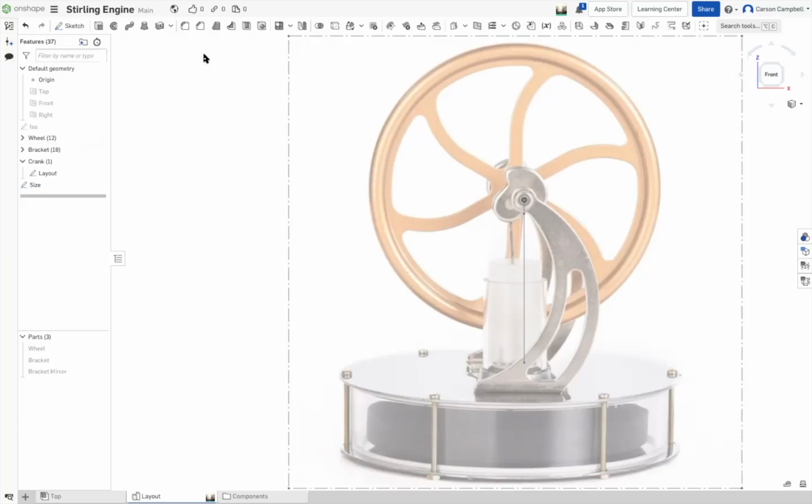It's also one of the reasons why I don't like dealing with US dimensions, because their nominal is in the middle of the tolerance zone. I like the European way of doing it, where you establish 3mm as your nominal, and you work higher on some items and lower on some items. To me, it's just cleaner to work in your tolerance zones using the European standard.